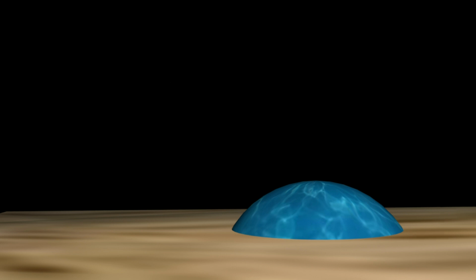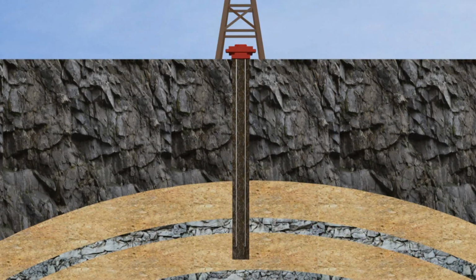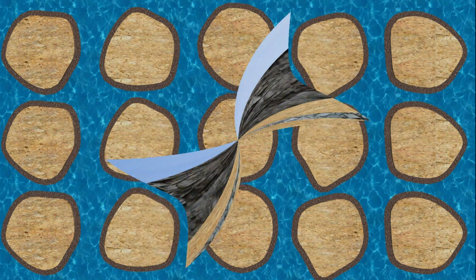Quantification of wettability by any method requires lab tests. Unfortunately, wettability of the core can be altered before reaching the lab by several reasons. First reason, it can be contaminated by drilling mud. Second reason, pressure and temperature changes due to the core trip from the reservoir to the surface can cause fluid composition changes, and hence causing precipitation of asphaltenes and waxes, which lead to wettability alteration by coating rock grains.